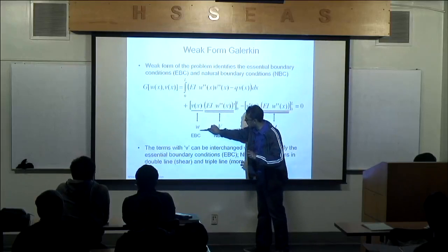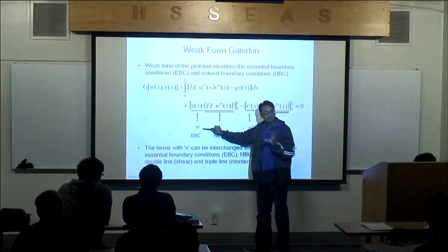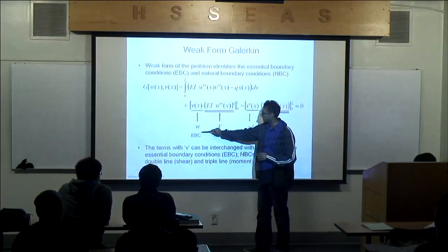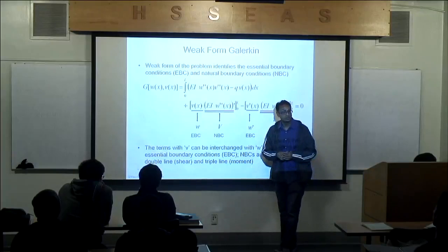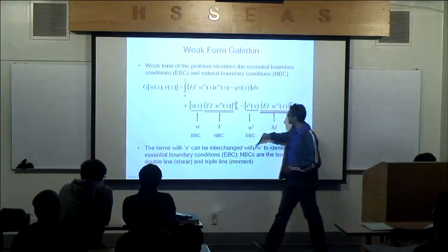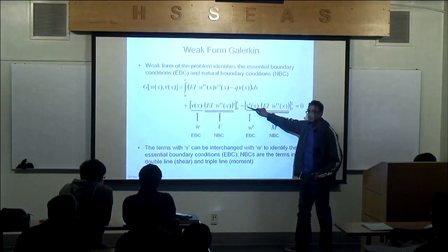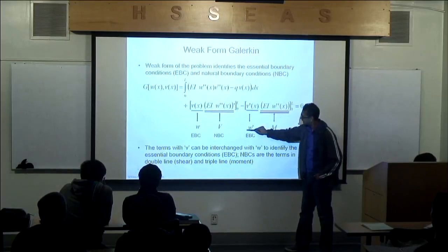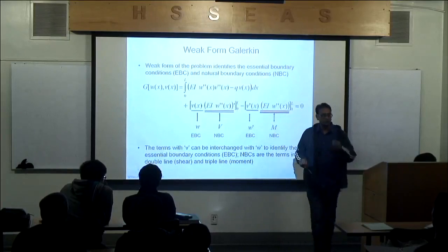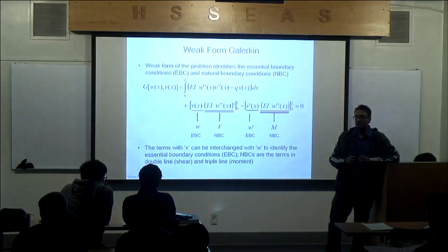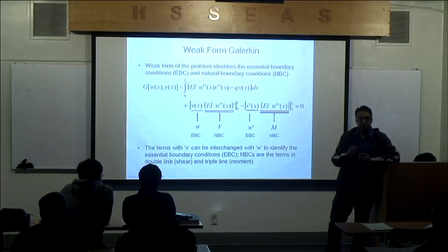If you do that, then if I have anything specified on this W, that'll make an essential boundary condition. If I make W, for example, 0 at x equals 0, that makes an essential boundary condition. That's V right there. For V prime, again, I focus on the V, and I see a prime. So I'm going to switch this to W, and I have W prime. This quickly tells me that anything specified on W prime becomes an essential boundary condition. So you can quickly identify what is essential and what is a natural boundary condition by constructing the weak form.